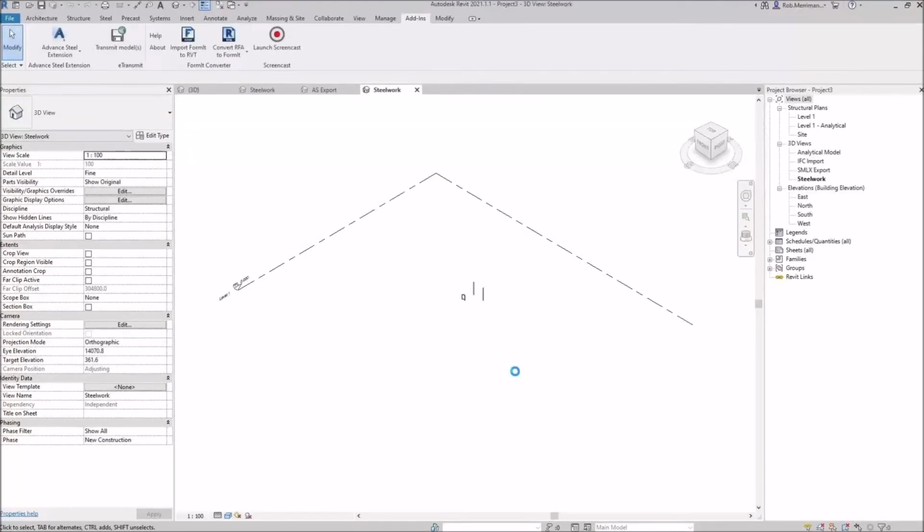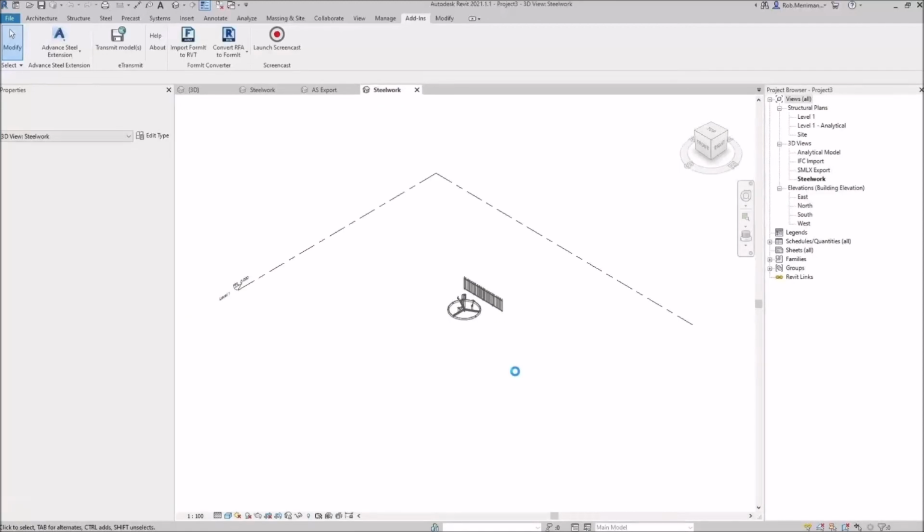So I will map it to a different size, but if it doesn't exist, then in reality we should be adding that size to the family or creating a new family to get our mapping correct. So if that dialog comes up and you're not happy with choosing a different section size, take a note of everything and then we can do some Revit family editing before we actually do the import.